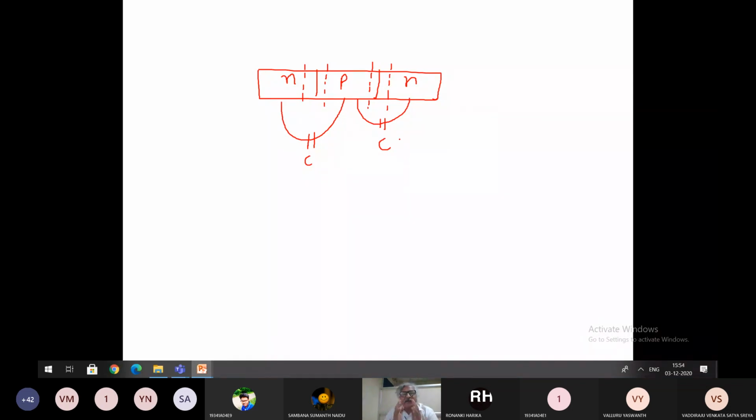So these are called inherent capacitances, because they are created internally. You have not intentionally connected any capacitor here, but due to the construction of the transistor, you will find these types of capacitances internally. So they will also take part in affecting the frequency response, right?